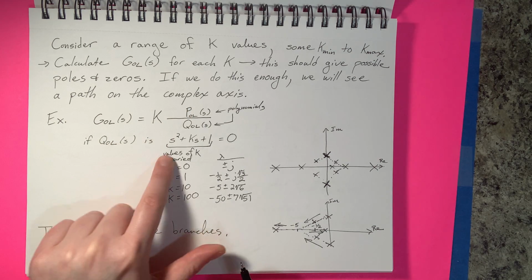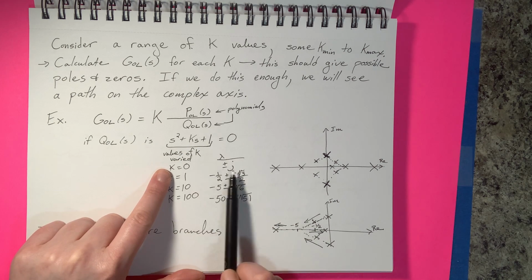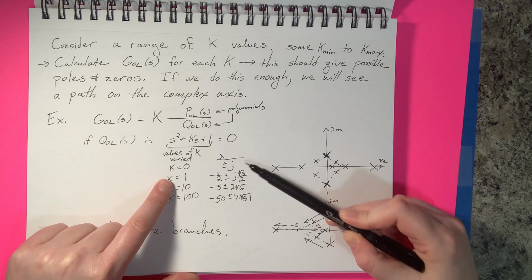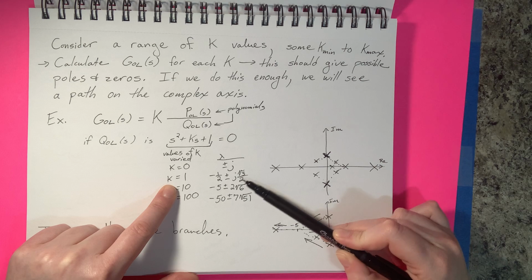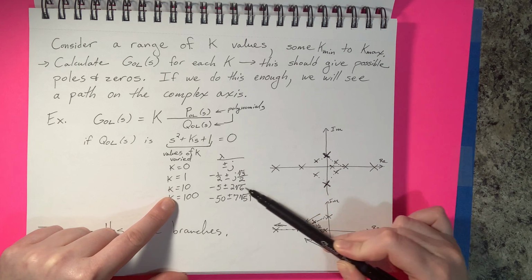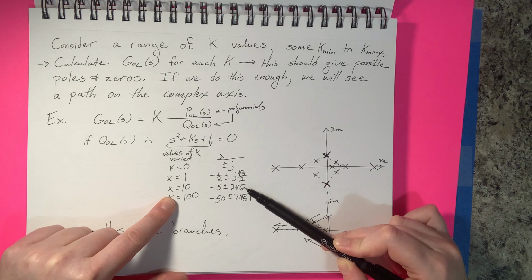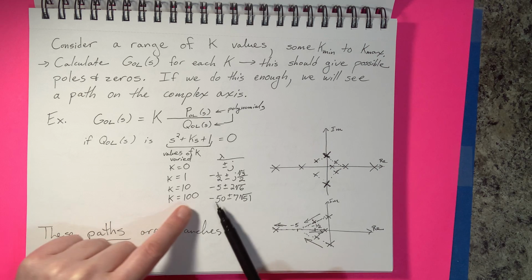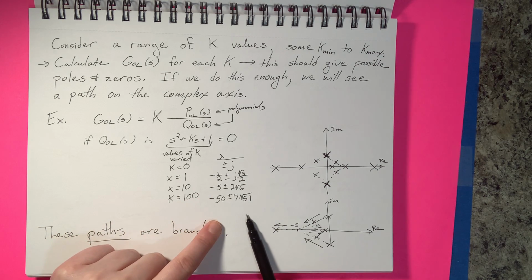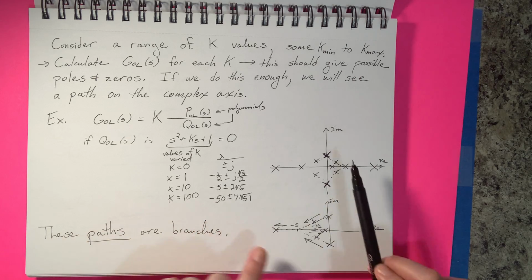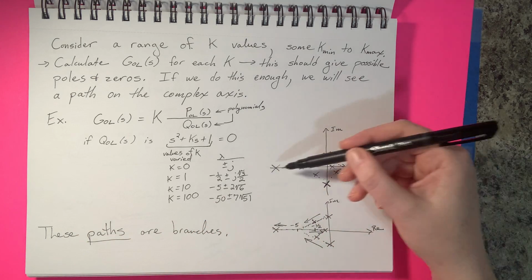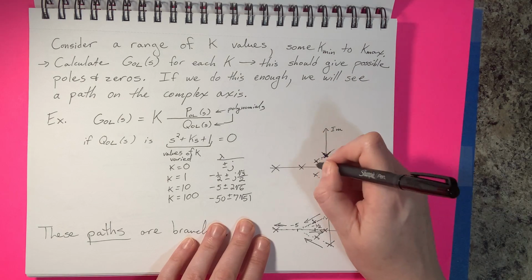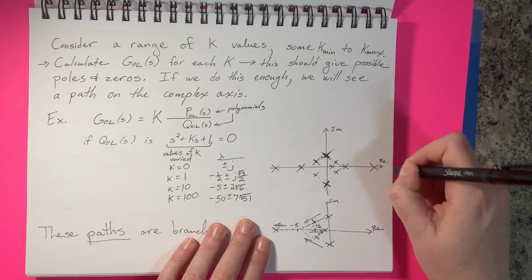And we can see as we vary the value of k and solve for these roots right here, that they go from being an imaginary pair to just a complex pair, so they have a real part now, and then they go to a strictly real pair, real distinct values, and then they stay real distinct values as we increase k. And if you plugged in further k's, you would see that they would continue to increase in magnitude, but they would stay real. So you would normally just plot, and here this is just a plot of roots that I've just tried to show, that you would just mark on the axis where these are heading to, okay?